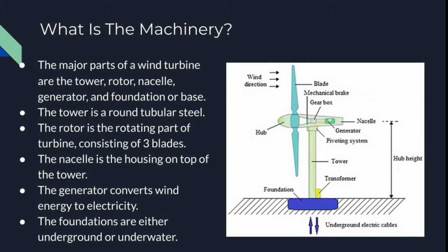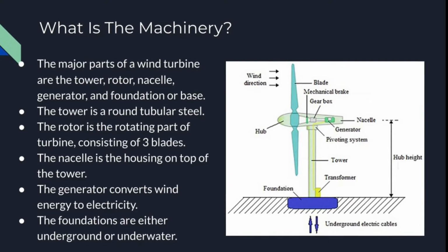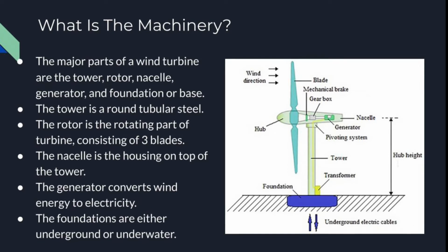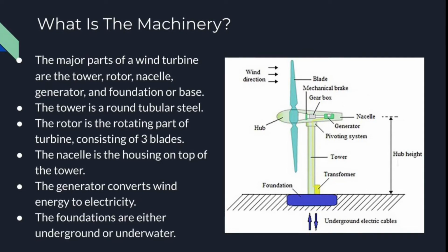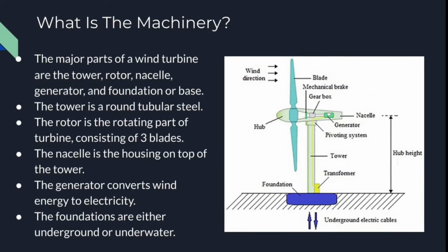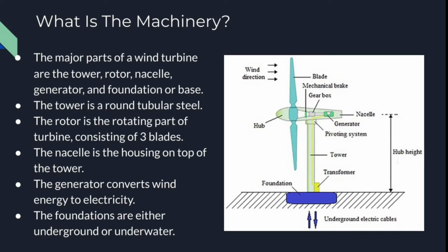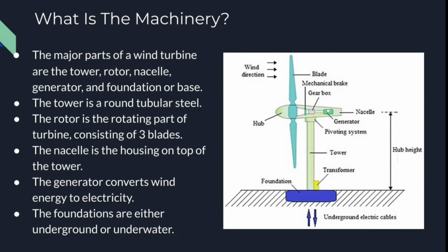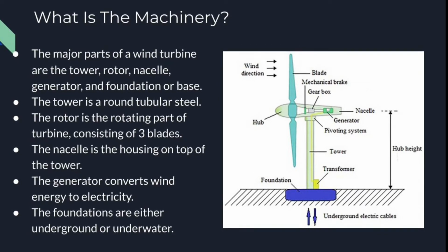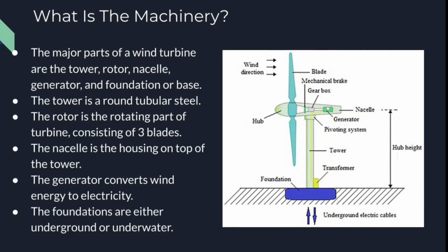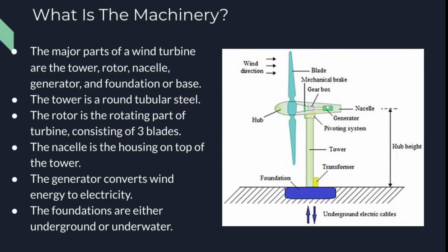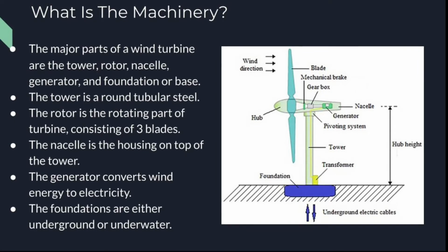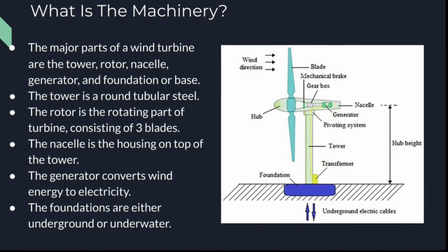The foundation is under the ground for onshore turbines. It cannot be seen because it is covered by soil. It is a large and heavy block of concrete that must hold the whole turbine and the forces that affect it. For offshore turbines, the base is under the water and cannot be seen. In offshore turbines that are well into the sea, the base is floating, but it is of sufficient mass to support the turbine's weight and all the forces exerted on it and to hold it upright.